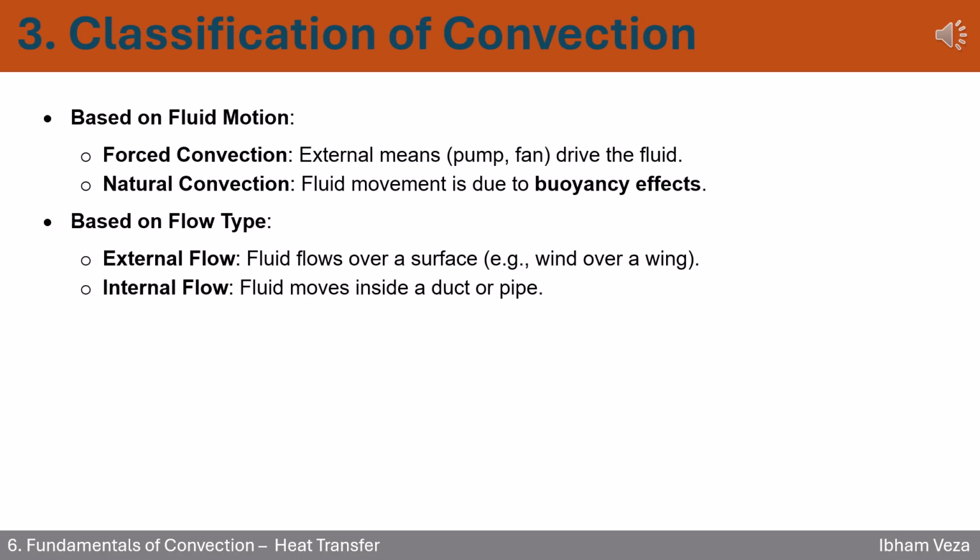3. Classify convection like a pro. Let's simplify convection by classifying it smartly. First, based on fluid motion. Forced convection happens when pumps or fans push the fluid. Natural convection occurs naturally, driven by buoyancy effects, like hot air rising.